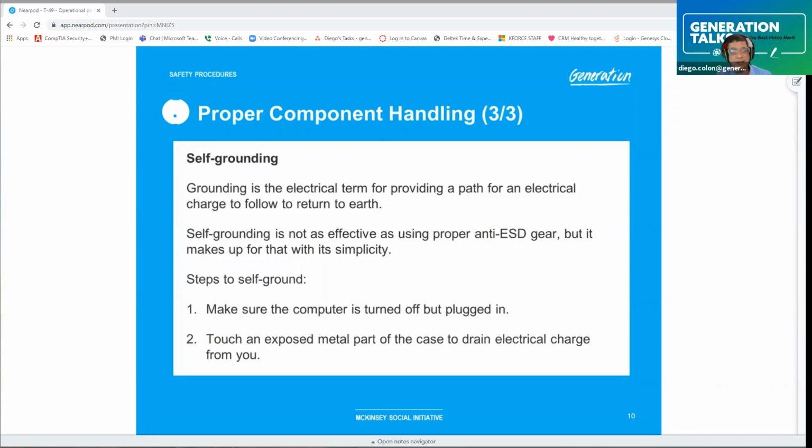I understand the book does say that, fully aware of that. But unfortunately, us old school, I just don't trust 110 volts just flying in there by mistake and something happening. So real world, unplug it. Testing, plugged in. I doubt they're going to give you that type of question where they're going to try to mess with you. In a real world scenario, unplug everything because you don't know which ones can and which ones can't.